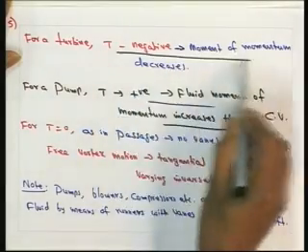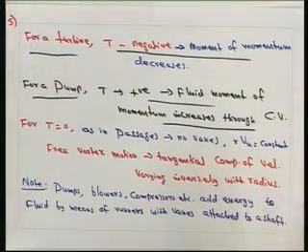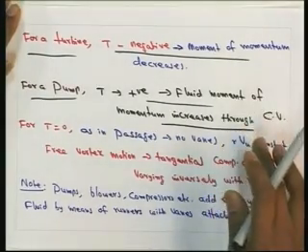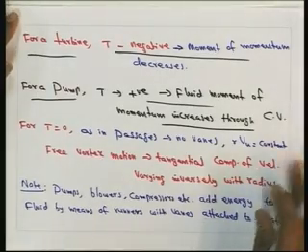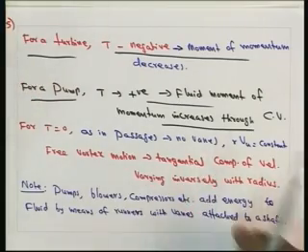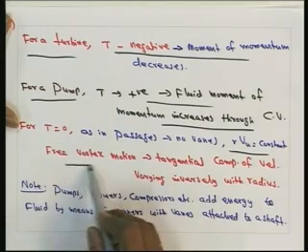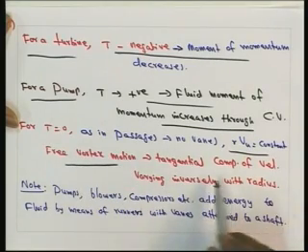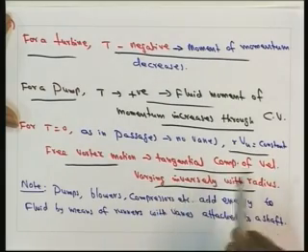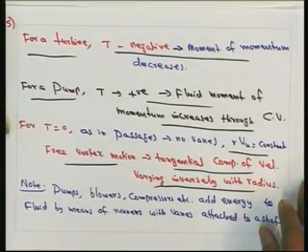In the case of a turbine, momentum decreases. So, this is the essential difference between a turbine and a pump. The moment of momentum decreases for a turbine, and increases for a pump through the control volume which we consider. And if T is equal to 0, as in passages where there are no vanes, we can see that R VU will be constant. So, a free vortex motion, in which the tangential component of the velocity varies inversely with radius, is formed. This is the so-called free vortex motion where T is equal to 0, as in passages where there are no vanes.